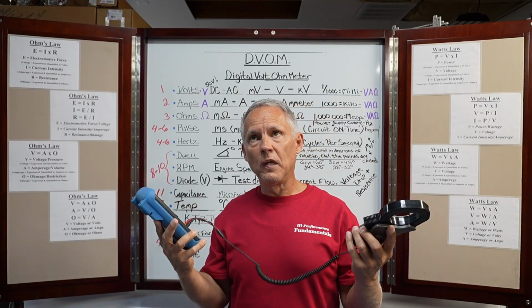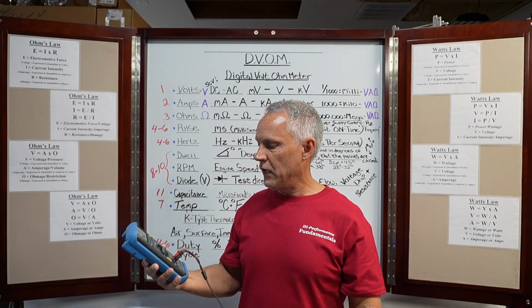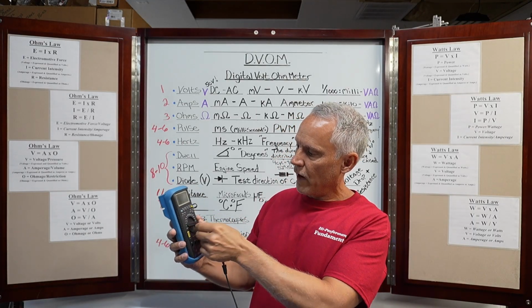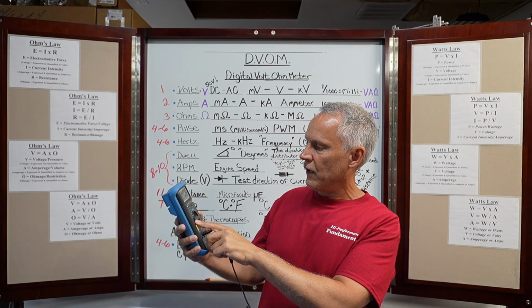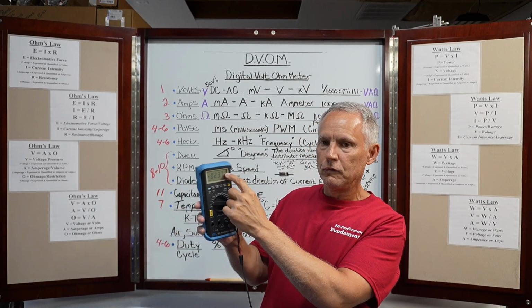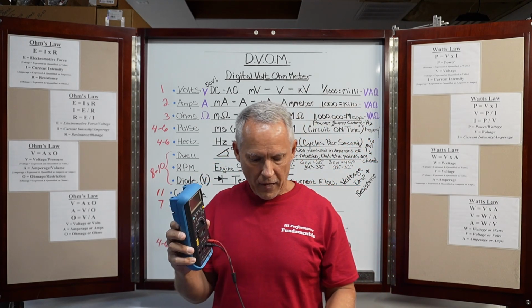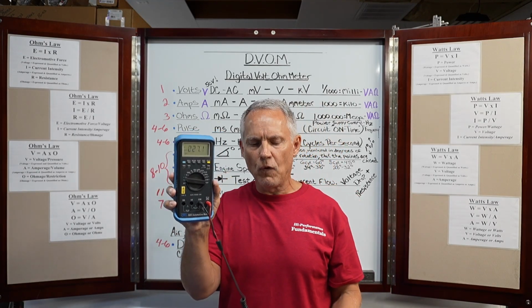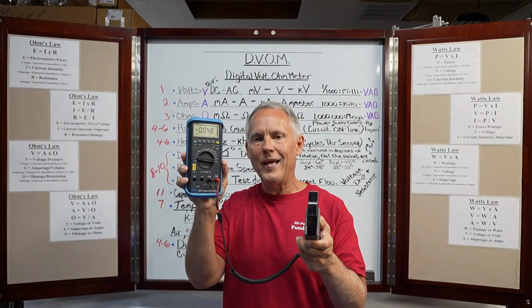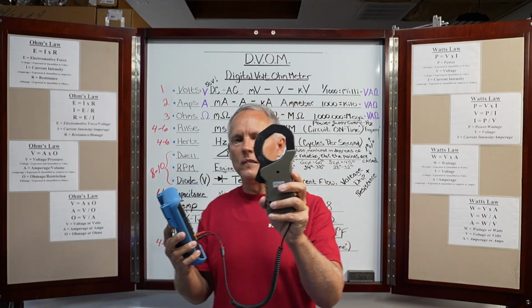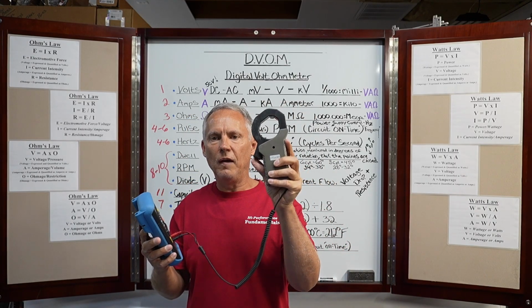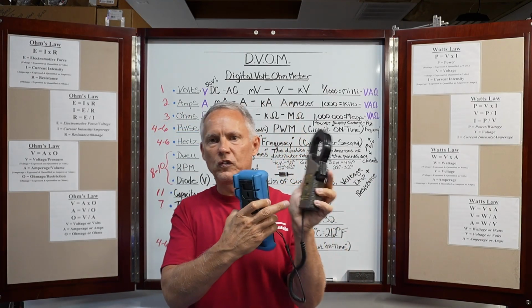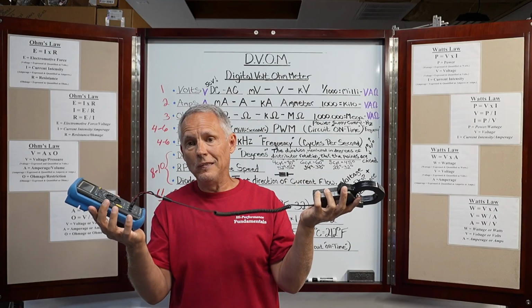All right, so if 1 millivolt equals 1 amp, well then we're going to want to be on the millivolt scale. So when we go over here to voltage, we'll go to direct voltage, right? And then on a direct voltage scale, we're going to select millivolts, right? As that produces a voltage, we'll be able to read it there. So for example, if that says 20 millivolts, we know that that circuit is producing 20 amps of current flow. So basically this is an inductive ammeter that produces a voltage. This measures the voltage. You simply calculate the voltage in relation to the scale that's on the inductive ammeter. That's basically how it works, right?